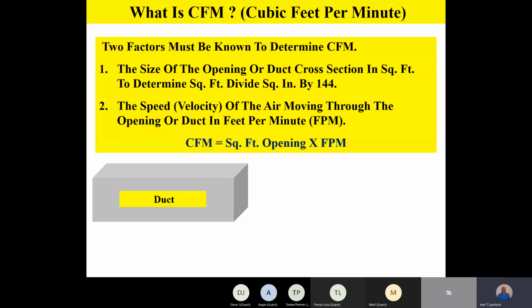So in other words, if I've got a 13-inch round duct in our example on the PowerPoint, we see that an equivalent rectangular duct might be something like a 10 by 14, or maybe a 15 by 11, and so on. You guys can kind of see where I'm looking at on the bottom of the duct calculator. So where those lines line up together, you can find that you've got a different size duct.